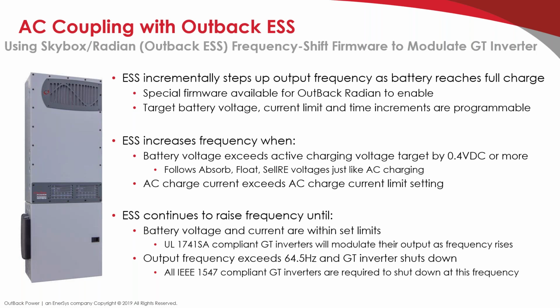I've done a lot of testing with this, and when you go down to a really low level, so there's a lot of extra energy coming from the grid-dependent inverter, this frequency-watt modulation technique works pretty well. It's not as well regulated as when you're DC coupled, where we can control more precisely. But for emergency backup, which is what I recommend for AC coupling, I do not under any circumstance recommend AC coupling full time. Without the really tight regulation, it's going to be hard on your batteries over time. If you're just doing it a few weeks out of the year, probably no big thing. But I do not recommend AC coupling on a daily basis.